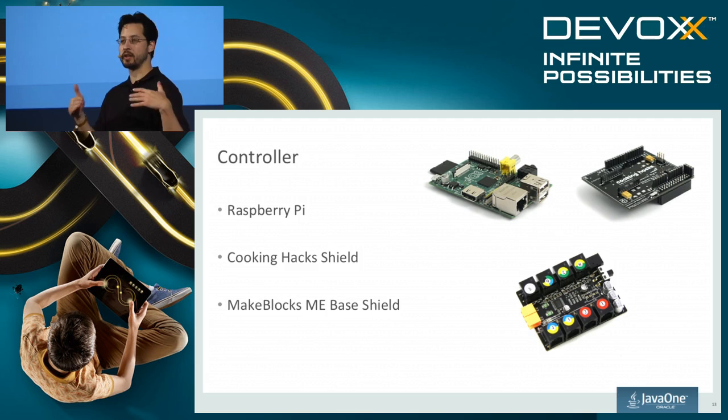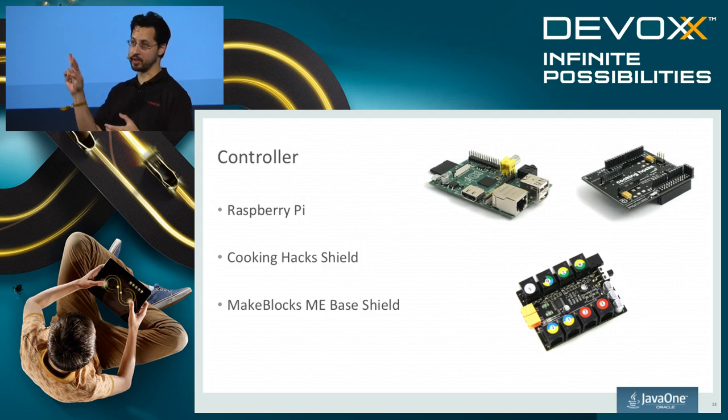Noticed at the beginning he was going about half speed, and then I increased his speed, cheating slightly on the last couple laps. So the way pulse width modulation works is you can adjust the power given to the motor by turning it on and off, and it does two things. One is it reduces the actual power to the motor, so it uses less energy since you're pulsing it on and off, but it also allows you to control the speed fairly reliably. So you can use this to speed up or slow down the motor.